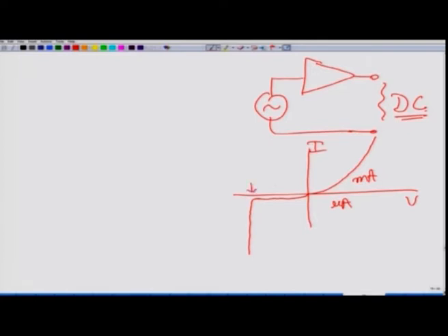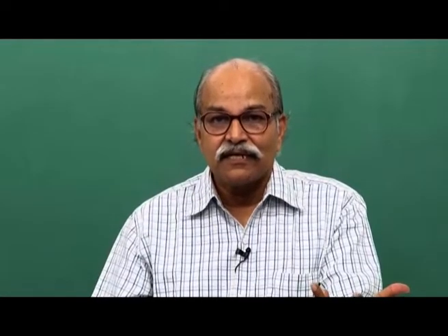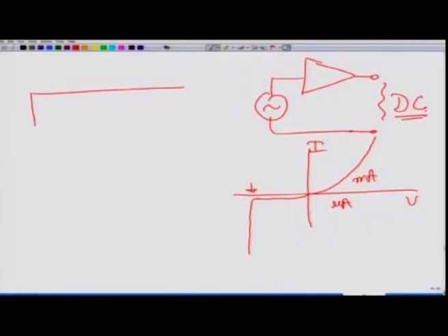So, if the reverse bias voltage is high, then you suddenly see that a lot of current is going in that reverse bias direction. I also talked about the mechanism of that. If you have this Pn junction, and in this Pn junction you have this depletion region, and in the depletion region you have electric field.